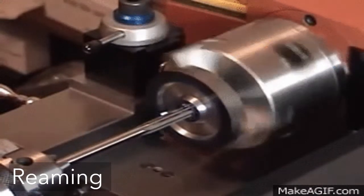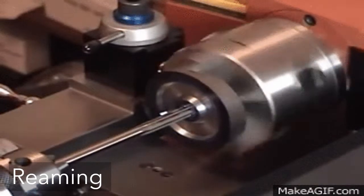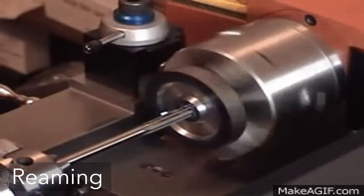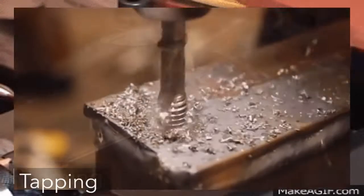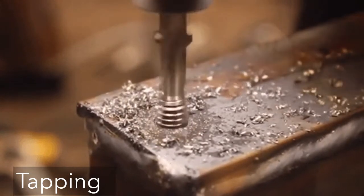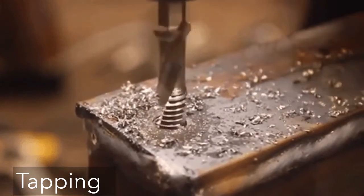Reaming is used to slightly enlarge the hole, to provide a better tolerance on its diameter, and to improve its surface finish. The tool is called a reamer, and it usually has straight flutes. Tapping is performed by a tap and is used to provide internal screw threads on an existing hole.